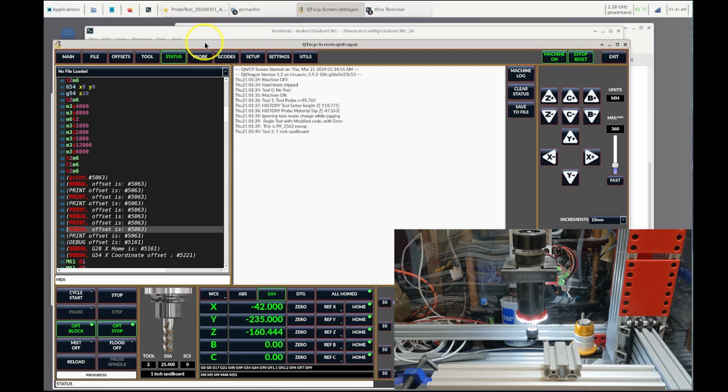I think the error handling, the positioning of it, is actually quite good, and I have used that in a pull request that I'm preparing to return the tool head back to its original point when the tool change was called. But this change to G38.2, I believe, is ill-advised. That's my opinion, and here's the test.